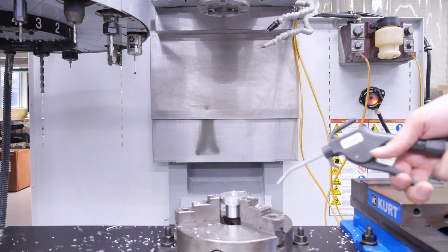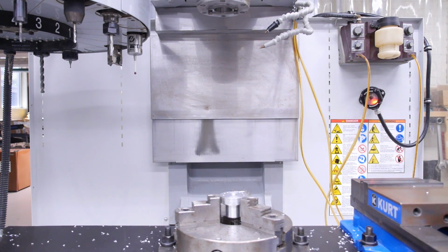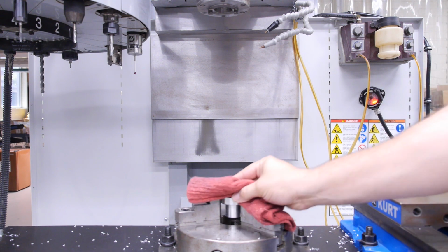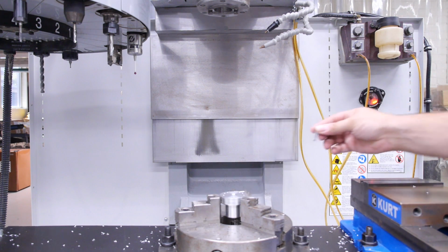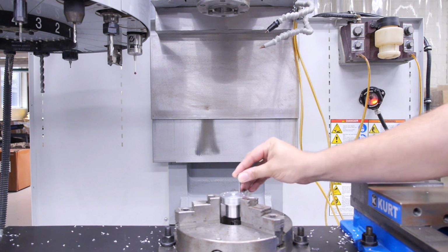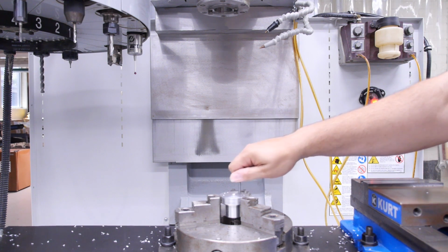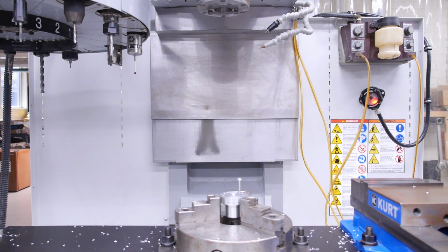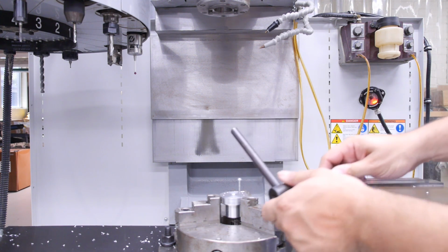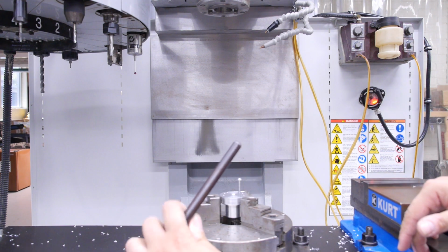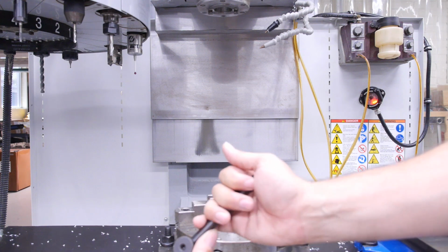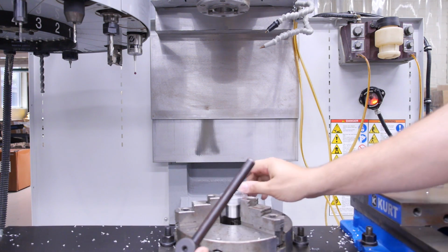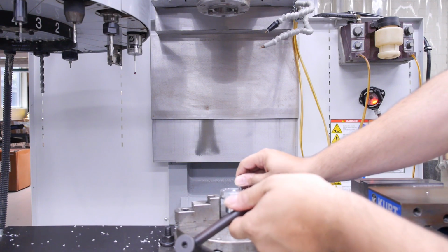After blowing the chips off the part and wiping the oil off of it, you should use a 10-24 screw to check the threads, and the screw also makes a convenient handle to hold on to when removing the part from the vise. If unloading the part by yourself, be careful not to drop it accidentally into the center of the vise.